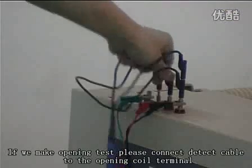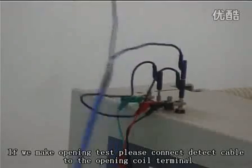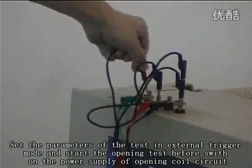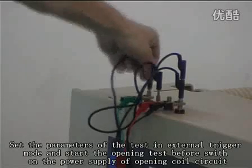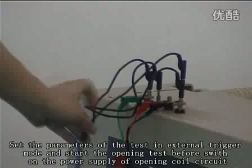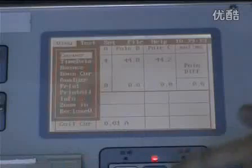If we make an opening test, please connect the detect cable to the opening coil terminal, set the parameters of the test in external trigger mode, and start the opening test before switching on the power supply of the opening coil circuit.